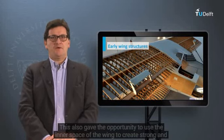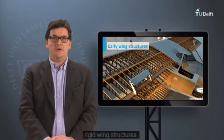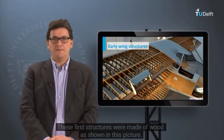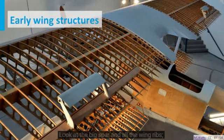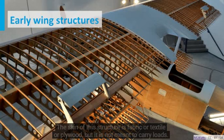This also gave the opportunity to use the inner space of the wing to create strong and rigid wing structures. These first structures were made of wood, as shown in this picture. Look at the big spar and all the wing ribs with many holes to create a lightweight structure. The skin of this structure is fabric or textile, or sometimes plywood, but it is not meant to carry loads.